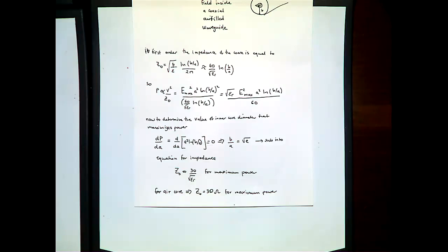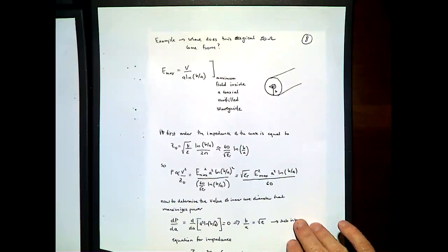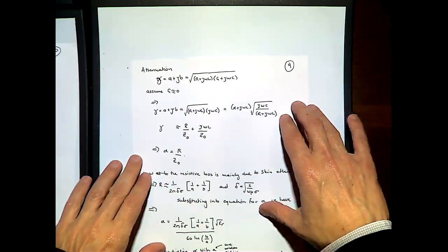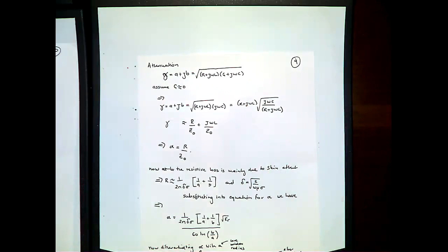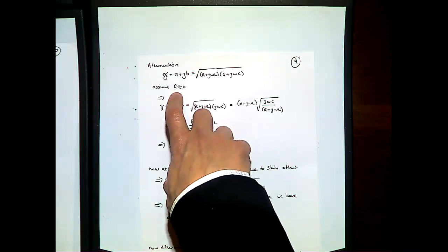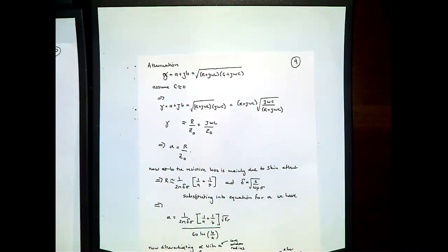What's going on here? Maybe it's not to do with maximum power. Maybe it's got to do with minimum attenuation. So let's look at what happens at minimum attenuation. For this same piece of coaxial cable, I'll work out the propagation constant, and in order to simplify the mathematics a little bit, I'll make the term G, which is the shunt conductance, equal to 0.